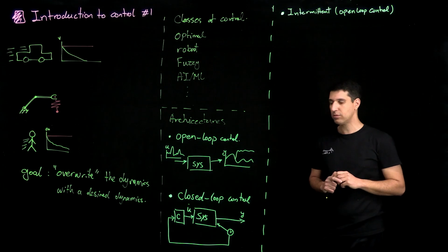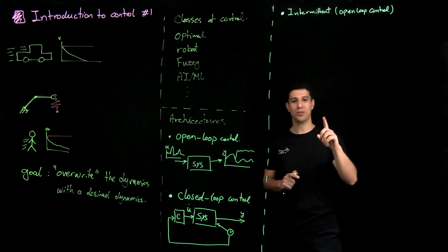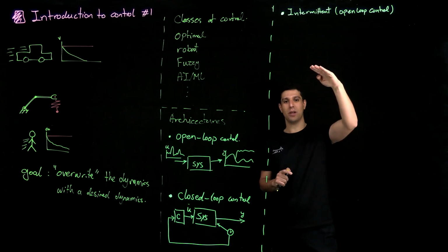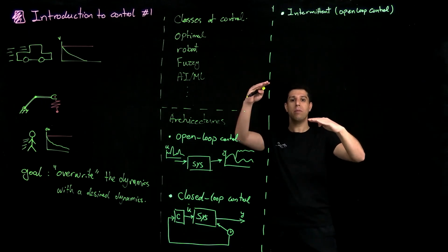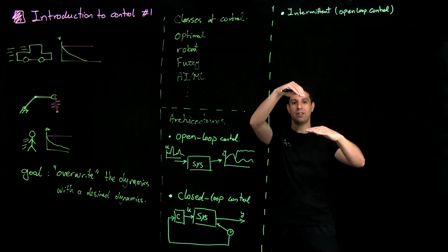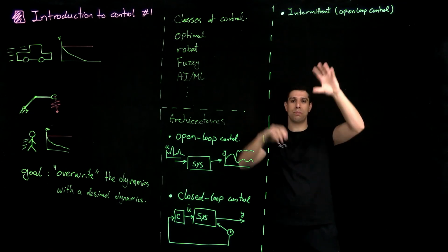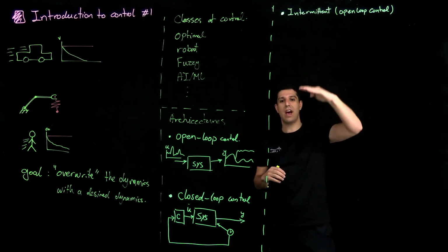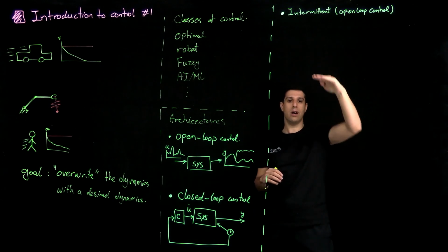Another example, a funny one, toilet flush. As you flush, the water level drops, and at the same time the water starts to come in to fill it up again until it reaches a threshold, those buoyant things, and after a certain level of water, the valve is shut, so the water stays there until you flush again.